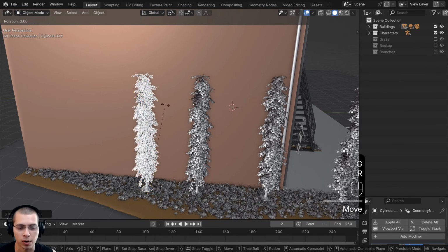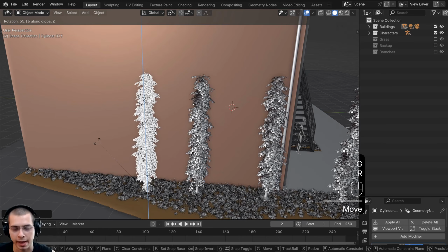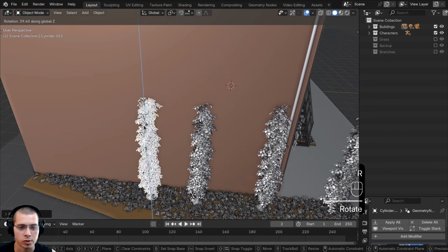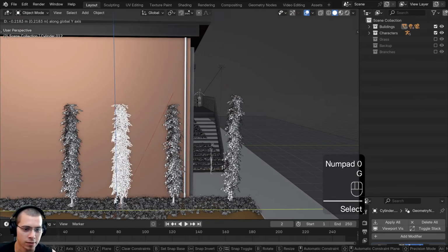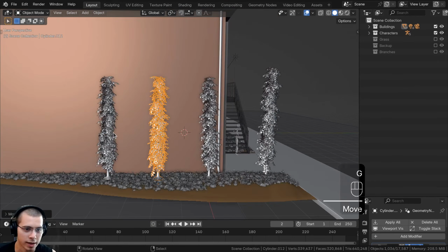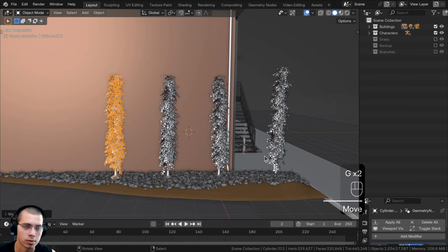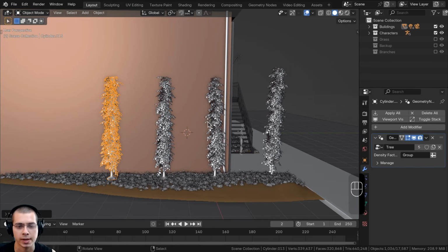However, I don't want to do this for all the trees because I do want to scale some of the trees and change how the shape of the tree is. So I don't want to do that for all of them. But if your scene is acting a bit laggy and all of these branches are lagging up the scene, then you could use Alt-D instead of Shift-D so it keeps the same amount of data. That way the file size will be less.